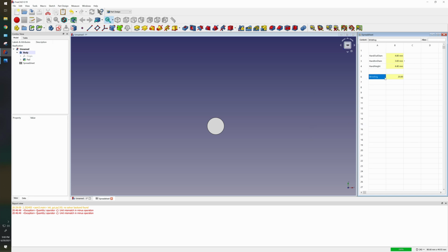So we want to get the right angle at 20 degrees. The question is, how do we want to do this? Before, if I wanted to make it at a 90-degree angle, I can go to the front view and sketch on a front plane and extrude it out. And the reason I'm working on a wrist first is, even if I have some bit in here, once I make the hole in there for the hand, it will just cut it out. So I'm not too worried about that. But I need to make an angle.